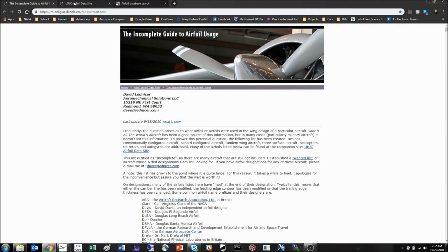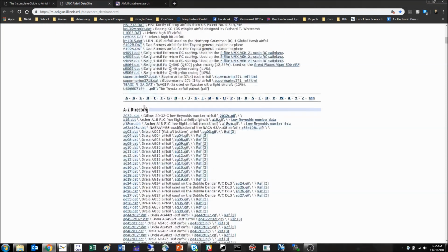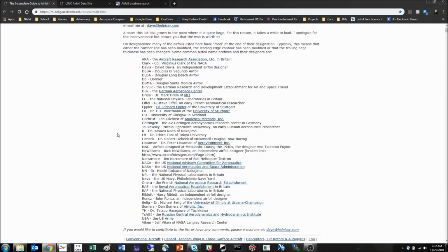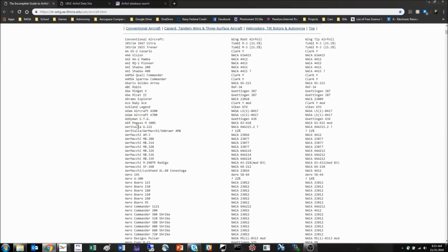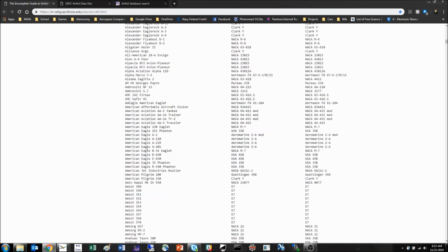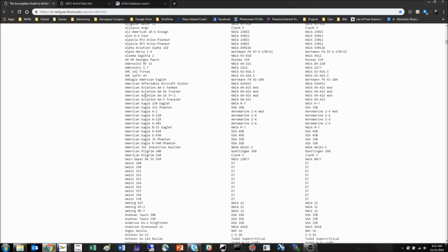Here we're looking at some of the resources to look for airfoils for different aircraft and how to find the actual airfoil files to read into VSP. So the first source that we talk about is a list of several different aircraft and the known or suspected root airfoil and tip airfoil for each of these. So if you happen to know what your example aircraft is or are, you can find them in this list, determine what their airfoils are, and then figure out whether or not you want to use a similar airfoil or something a little bit different.